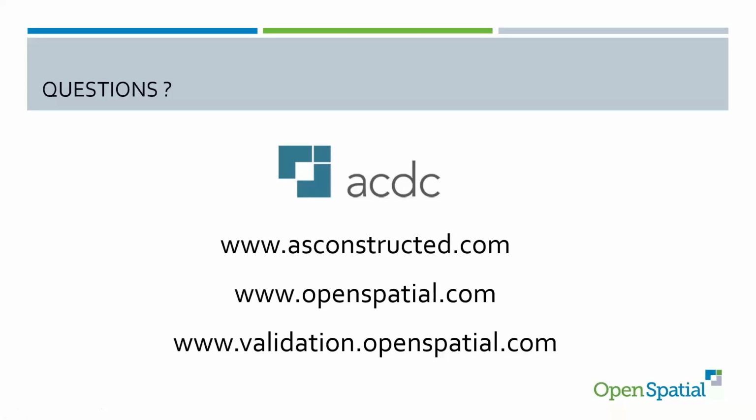Here's a question: can the CAD template be used by Trimble GPS devices, with a survey department that works in conjunction? So the short answer is yes. And the more detailed answer is you'll find that a lot of the templates that the surveyors use don't necessarily capture all of the data that GIS is going to want. So if it's a surface survey, they're going to go along and say, yep, this is a hydrant, or this is a sewer manhole, but they're not going to give you the diameter of the pipe coming in at the other end. But any data that is on the survey side, yes, you can pull that in.